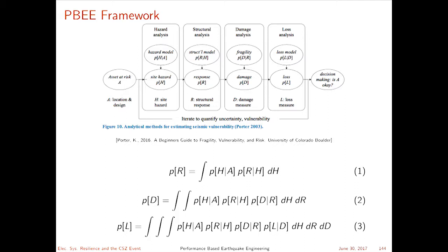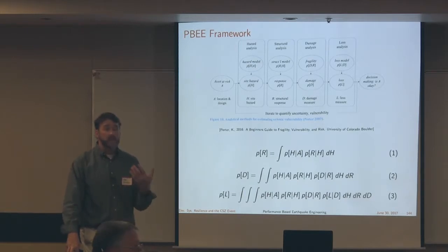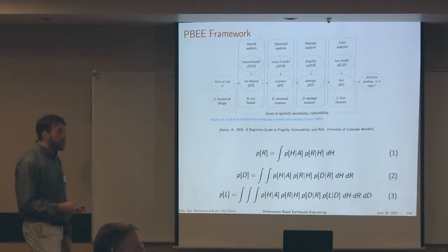When I have a probability of damage, from there I can determine a probability of loss, given that damage. So if the system has a certain amount of damage, what's the probability that it's in a certain loss state? What would loss states be? Loss state 0 might be that it works totally fine. One loss state might be that it's completely gone. Another loss state is that it's lost half of its load or something like that. Again, as the designer of this methodology, you have to determine what those states are, and we'll go through some examples of that.